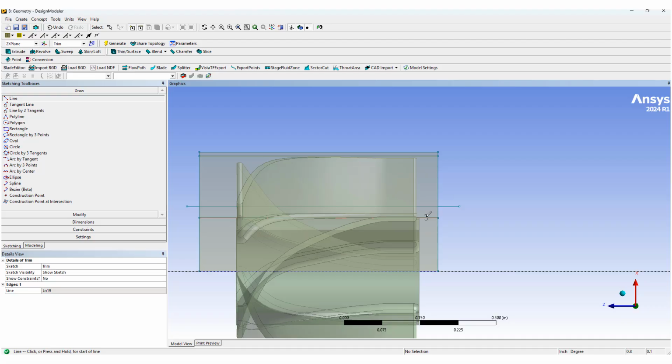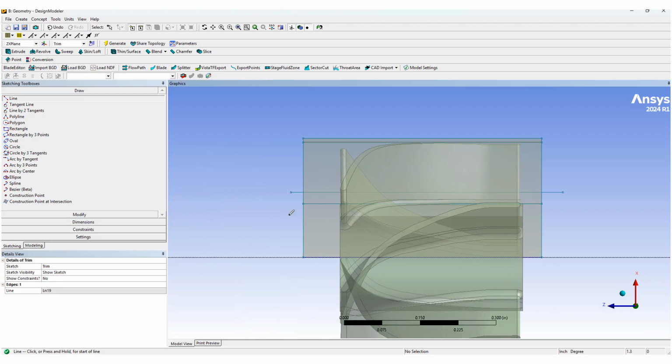And now we're going to use this sketch to cut the regions. Of course, before doing that, we're going to create a surface out of that, and that will be using the revolve function. So we will use this location to create a revolve surface, which is going to be another cylinder. Again, you have another option of maybe putting a cylinder here and then using the cylinder surface to initiate that cut.